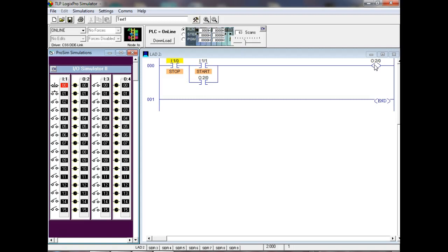We don't like to do that a lot. We don't like to use a lot of switches out in control. We like to use a lot of push buttons, even if they're simulated on an HMI panel. So what do you do? You go over there, you just touch the start, and then you let it go.